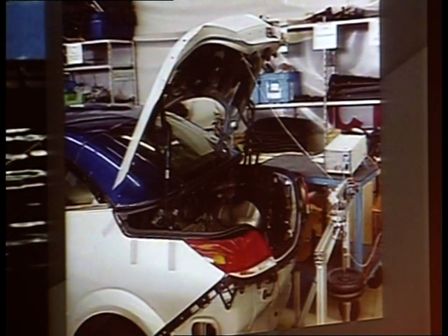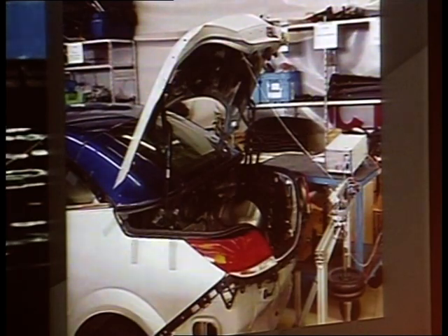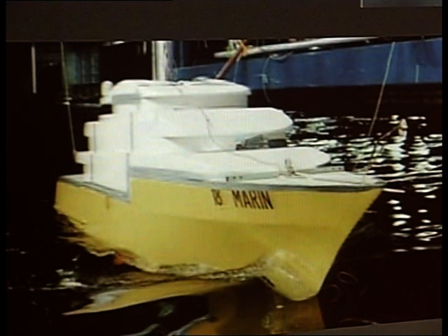But they can also use it with a laser scanner to check stuff like flush and gap on the body joints. Now the last one I show here is an important one. It's called ship model stability testing, where you put some LEDs on the ship model. You let the ship model go in a towing tank. You produce some waves simulating rough conditions like a 7-year storm or 10-year storm. And then you see how your actual ship, based on the model testing, is going to behave in bad weather.